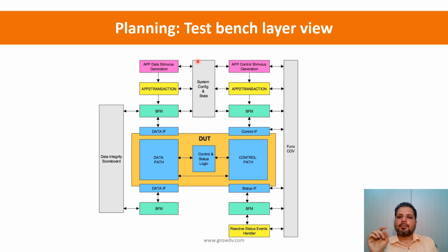And then typically between these two, both the data interface as well as the control interface generators, you use this intermediate shared global configuration and state. Configuration, as we briefly talked about, is the mode in which the DUT is behaving, and in the context of the test bench, it could be both one-time programmable configuration as well as configuration that we can dynamically program.